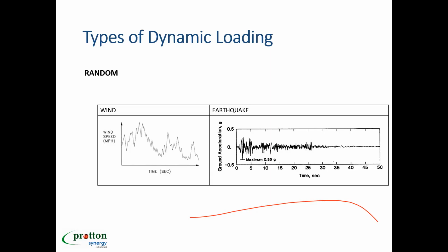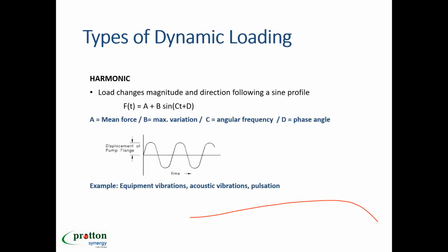And in time history, you actually know the data with respect to time, and you impose it onto the system. So the time history is, I would say, very close to the response spectrum analysis with a little bit of differences in the analysis method.